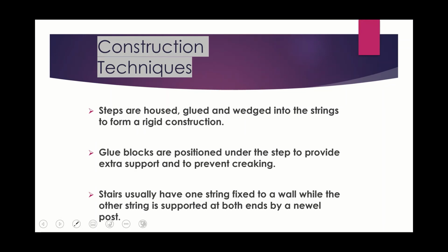So just the techniques involved, the steps are housed, glued and wedged into strings to form a rigid construction. Glue blocks are positioned under the steps to provide extra support and to prevent creaking. Stairs usually have one string fixed to a wall while the other string is supported at both ends by a newel post.